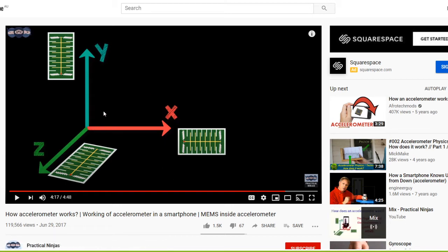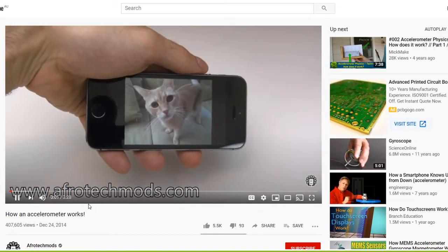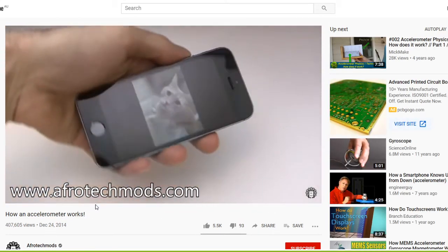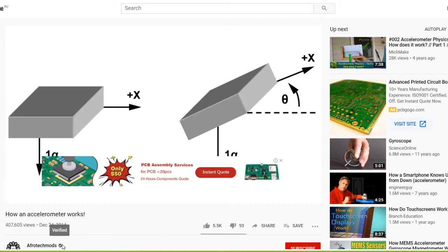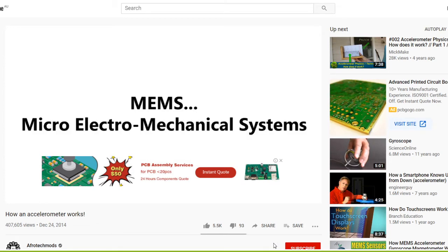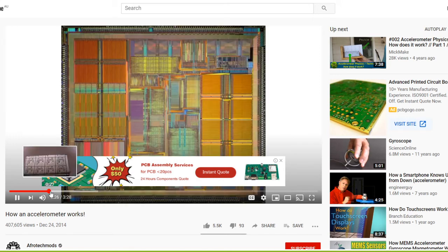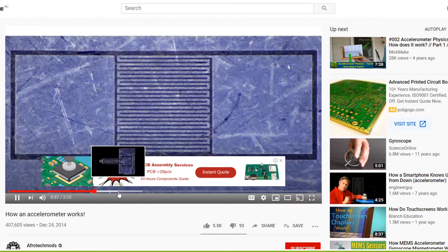But our accelerometer and gyroscope are all three-axis, so it's very complete. So it's good. You can also continue to look at this: have you ever wondered how your phone manages to know what direction you're holding it? It's using a device called an accelerometer. It works by sensing the acceleration of gravity, and then you can calculate what direction the phone is facing. But how does a piece of electronics sense something mechanical like acceleration? The answer is MEMS, microelectromechanical systems. MEMS manufacturers use similar techniques to those used in making chips.